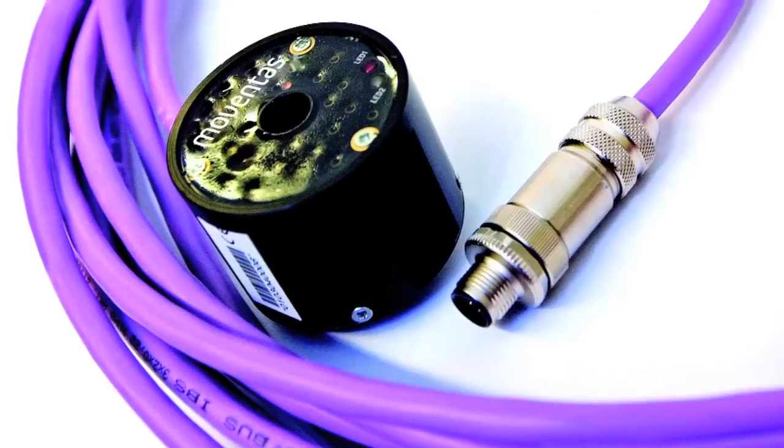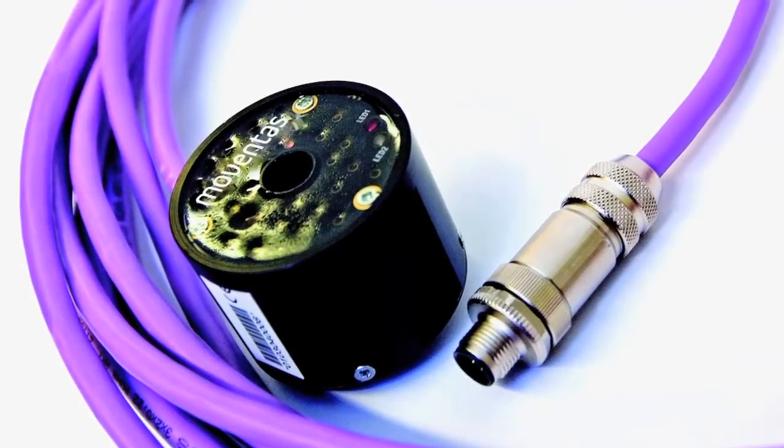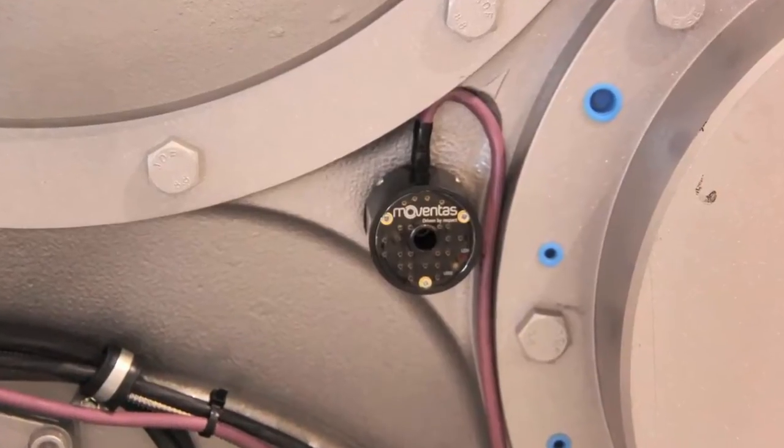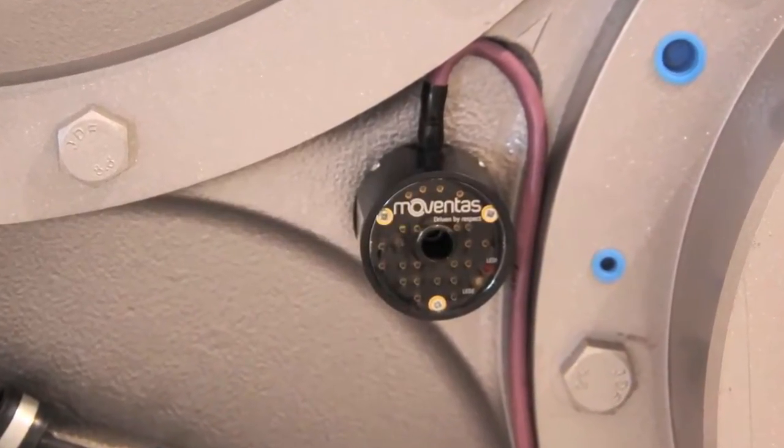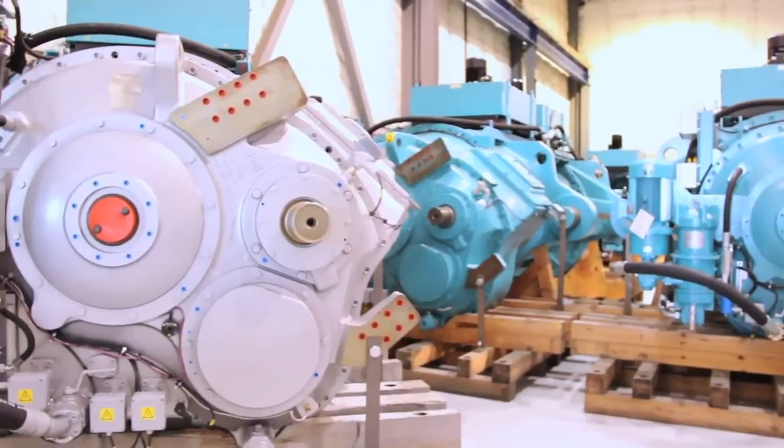Moventas has developed a vibration sensor called an IVS-20. It's an intelligent vibration sensor, and by intelligent, it has its own processor built into it that does all the FFT and gear-specific algorithms that are required for processing. It's a triaxial sensor. It has 3 accelerometers built right into it. So we're measuring horizontal, vertical, and axial all at one time. And this data is important because without the triaxial data, we don't know about misalignment or unbalanced conditions that might exist.